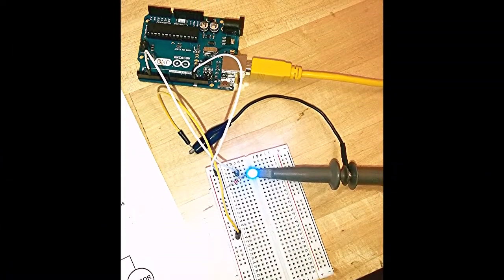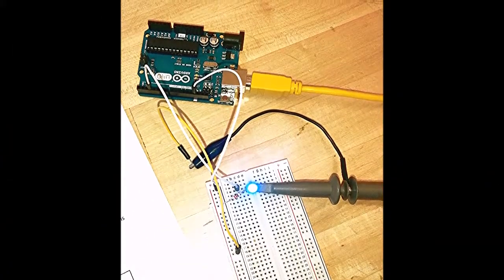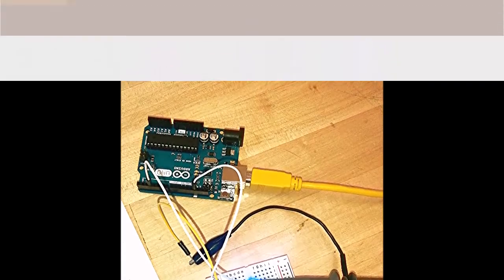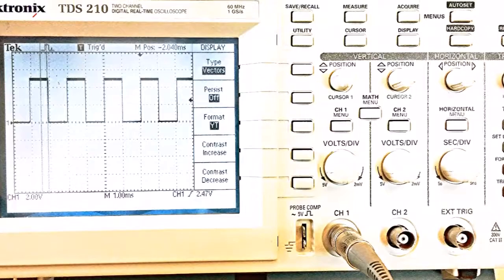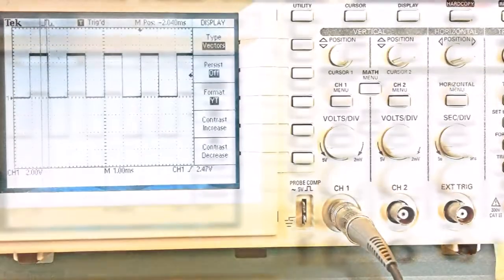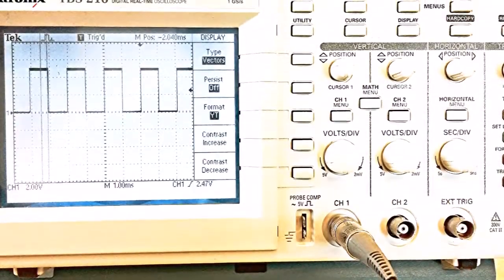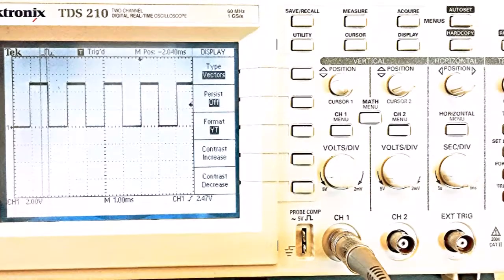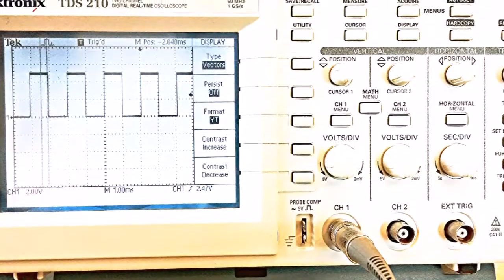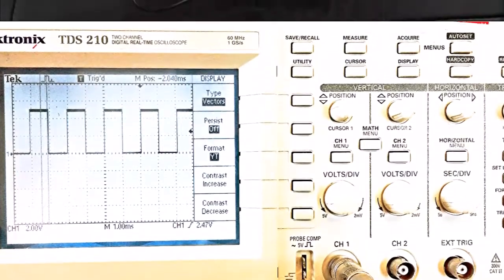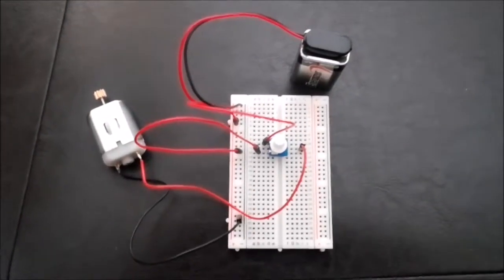Let's say I hook up the circuit to an oscilloscope, and then I type in 50 on my Arduino sketch. The oscilloscope would look half on and half off. That means the 50 is half of 100%, which is putting out 2.5 volts instead of 5 volts. The 5 volts would equal the 100%, and 2.5 equals the 50%, which means it's using half of its duty cycle.